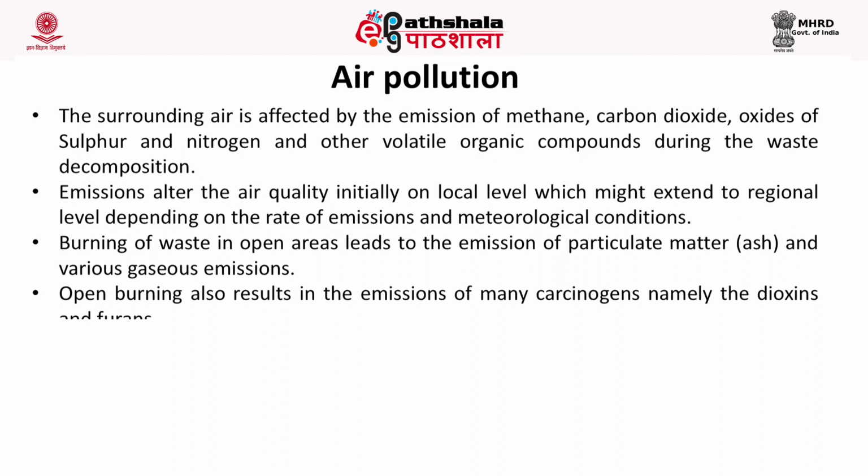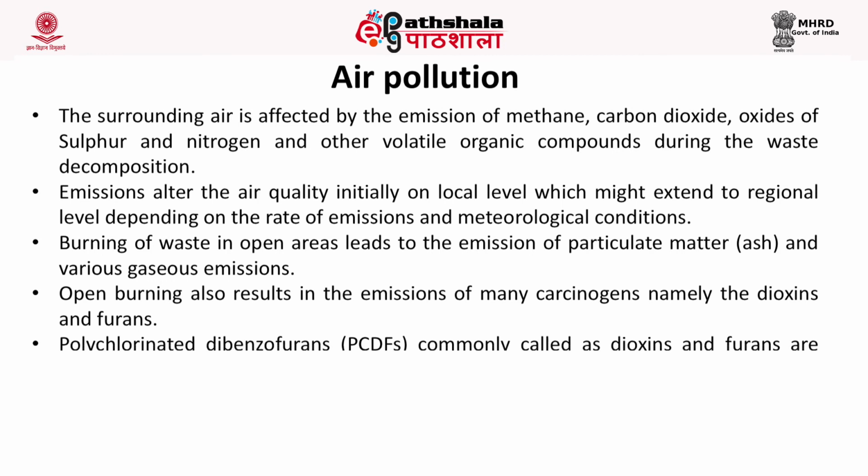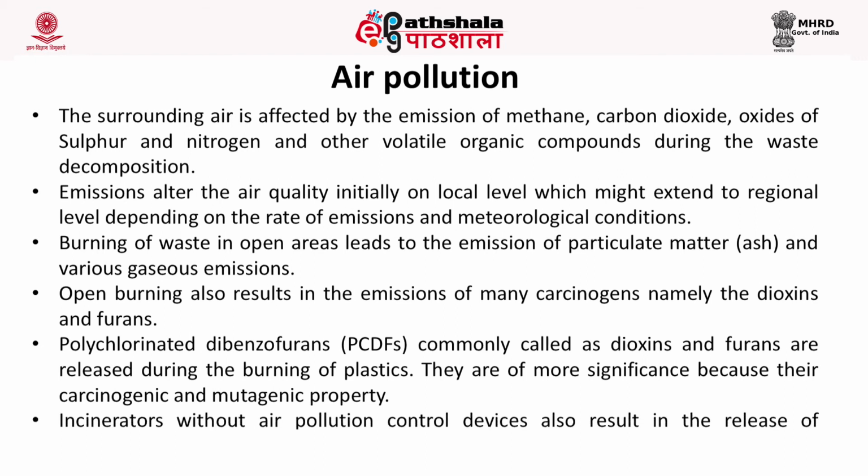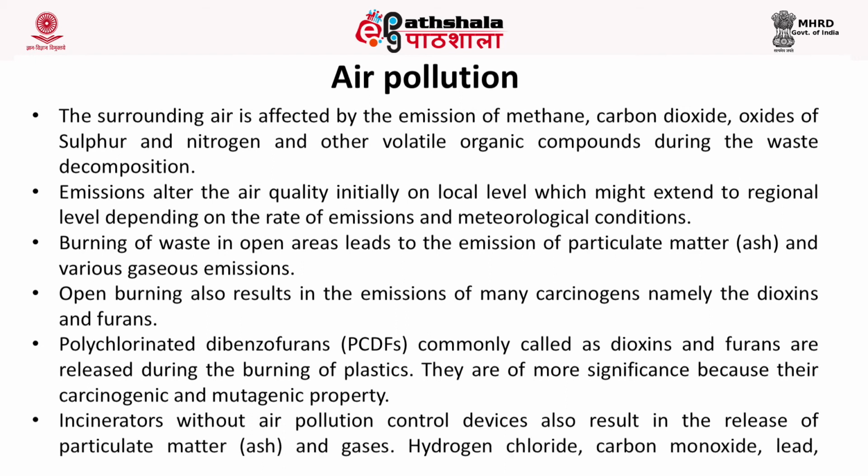The polychlorinated dibenzofurans, commonly called the dioxins and furans, are released during the burning of plastics and they show significant carcinogenic and mutagenic properties. Incinerators without air pollution control devices like the cyclone separators or bag filters will lead to the release of particulate matter, which is the fly ash. And also, if you don't have a scrubber or absorption unit, it will result in the release of various gases, which might lead to harmful effects.